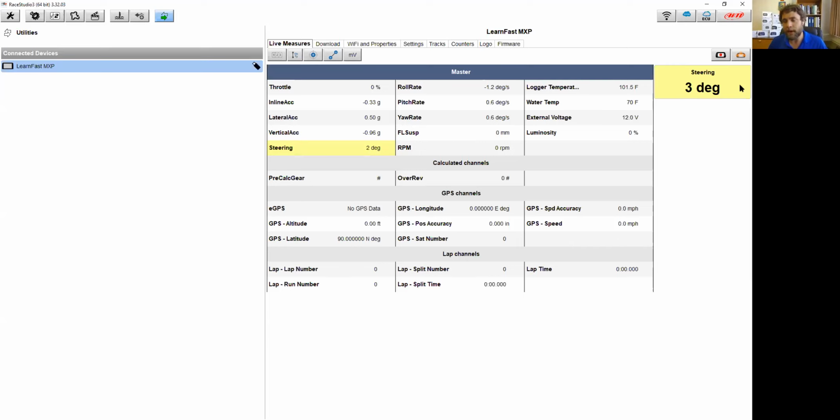And what's pretty neat now, Roger, if you spin that steering pod a little bit for us. So back over here into the live picture, you can see that's here. I put a little arrow where 0 is, like the piece of tape on the top of your steering wheel. So if I turn that thing about 90 degrees to the left, there's what you're seeing on the main screen, right? Right. So now you can see it pops in here and it gives us the 90-degree measure. So we know we're working on the right channel. It's a nice little way to check things out.